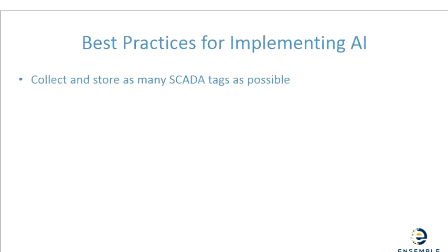One of the things that we would definitely recommend is that you collect and store as many SCADA tags as possible. We see lots of owners who don't collect all of the tags that are available to them. They want to keep below tag limits, which helps save some expense. But what we find is that the incremental cost of storing additional tags is very low, and that value can be very high. So we would recommend that turbine owners store as many data tags as possible. And if you haven't done that up till now, that's okay, but our recommendation is to start as soon as you possibly can.